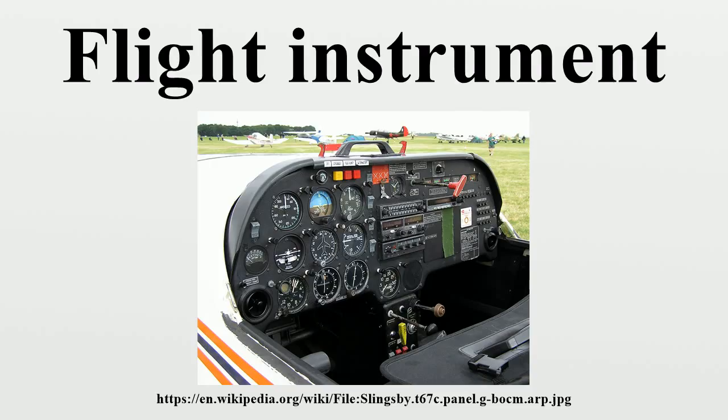Different significance and some other instrumentation. However, all 5 instruments are not equally important. Only the artificial horizon, altimeter, airspeed indicator and compass are imperative. Due to this, all passenger airliners are equipped with a battery-powered integrated standby instrument system, along with a magnetic compass. The vertical speed indicator, or VSI, is more of a good help than absolutely essential. On jet aircraft it displays the vertical speed in thousands of feet per minute, usually in the range -6 to +6. The gyrocompass can be used for navigation, but it is indeed a flight instrument as well.